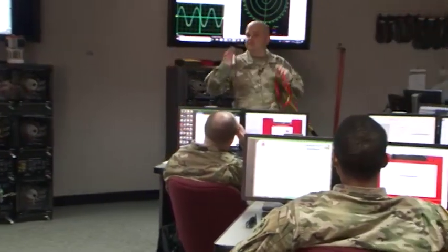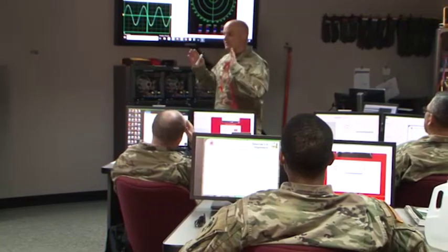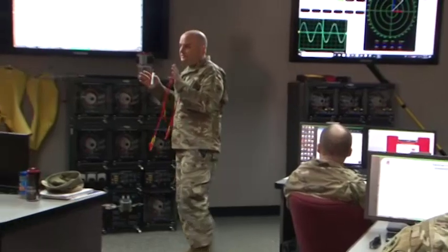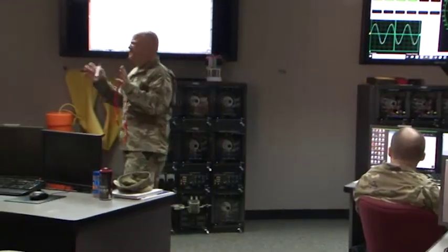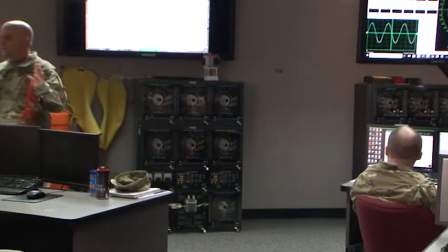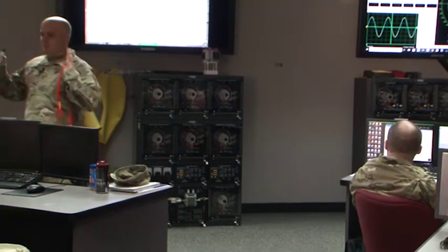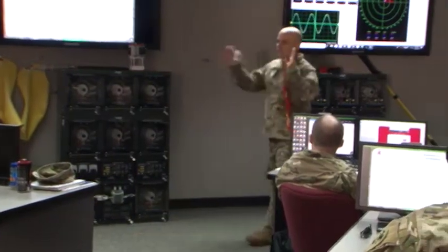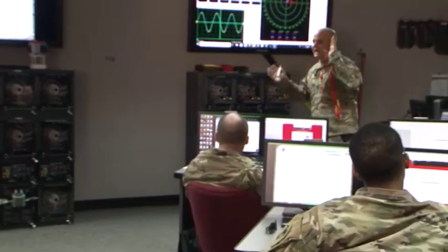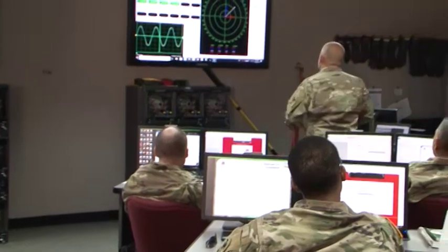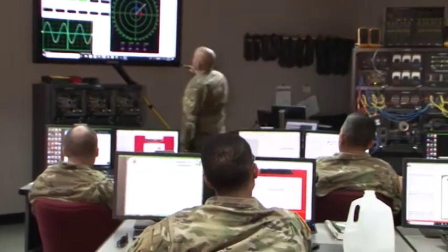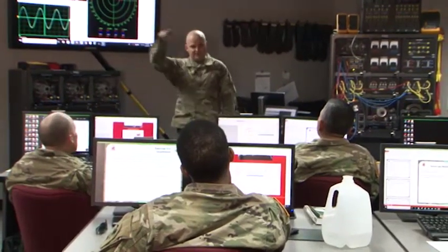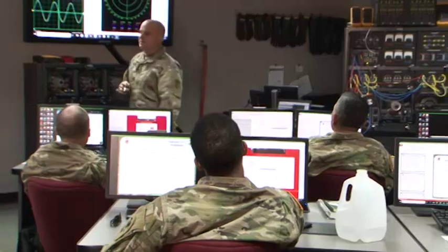The voltage shift, the angular difference between the voltage and current across the resistor is what, compared to the voltage and current relationship across the inductor? Are they in phase with one another? There's going to be a 90-degree offset there, right? So now you're seeing the results of vectorial differences between two being out of phase from one another. Right now I have I1 as reference. This is a series circuit. In a series circuit the current flowing through is the same, so we use that current as the reference.